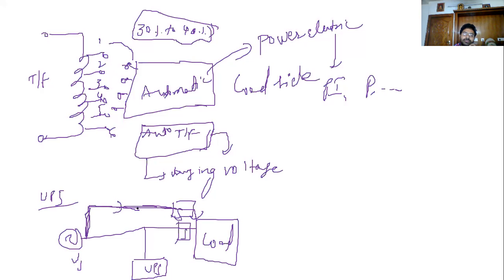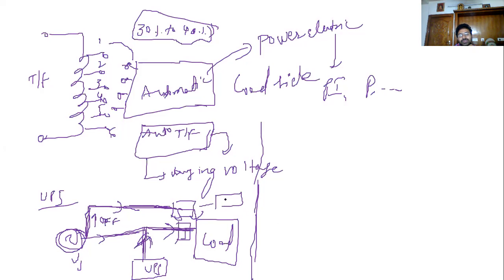If there is a fault in the system, or some interruption, the automatic controller of this switch will identify that and open this way. So this is open, or off, and then power goes in this direction and can supply power to this load. That's why you can maintain uninterrupted power to this load. Or you can also treat it as hybrid. In this case you can use some ferro resonance transformers, the constant voltage transformers, to maintain constant voltage levels at the loads.